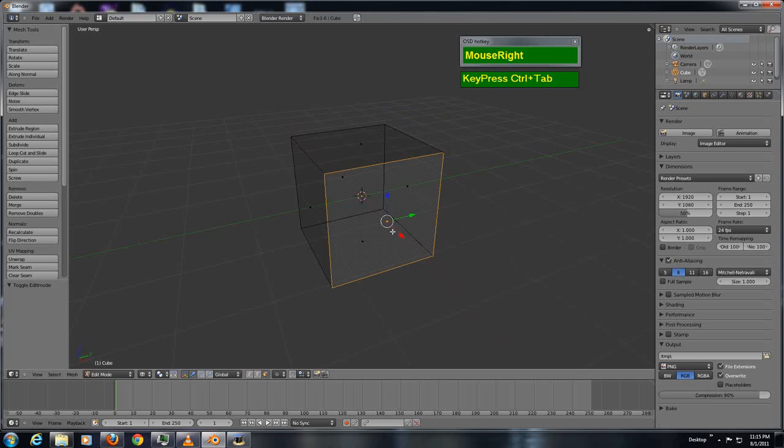And in a way, you can also do selection conversion. For example, right now this face is selected. If I want only the vertices to be selected, you can press Control Tab and go to vertices, and now you can see the vertices are now selected. Go to edges. Now only the edges are selected. So in a way, it can be very useful. For example, I select this edge, I go to vertex, now the vertices are selected. Okay, so now we know how to select the different portions of a mesh.